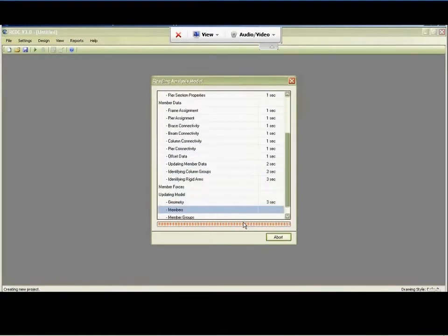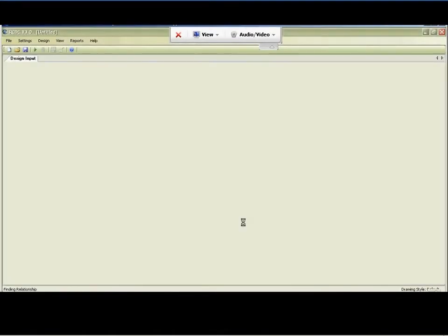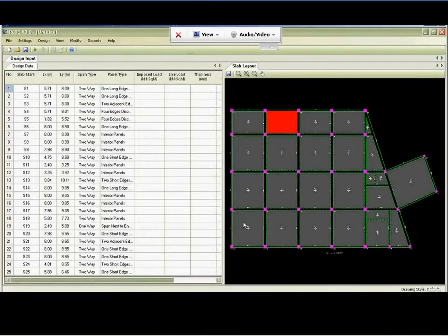I go to slab, and I select a slab, say story 1. Here, whether you model or not, the slabs are identified from the beam column geometry. So the software will identify the slabs. Here, as you can see, we've not modeled anything in ETABS. The software identified, or it could be in STAAD, where we never model slabs. It identified each small polygon, or the smallest of polygons, which could be slabs.